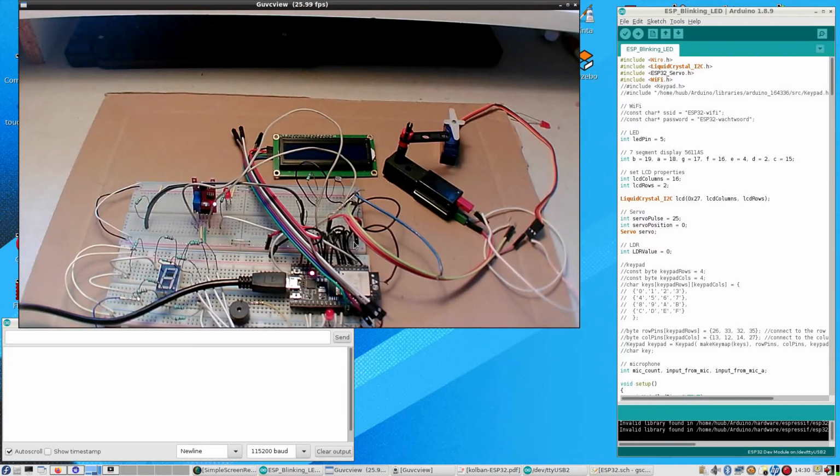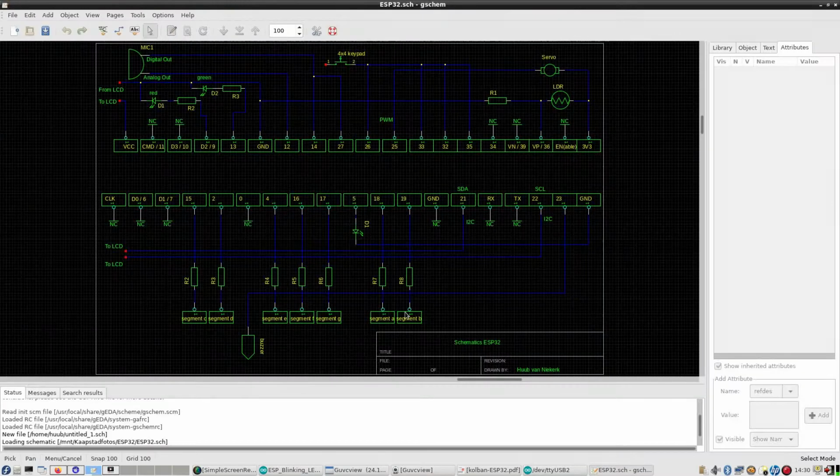And of course there's another complicating factor, because apart from the power that goes in here, from the manual, and I just noticed that because of the schematics, when you use USB power in, this one, the V in for 5 volts, automatically converts itself, or the controller of course, to V out.